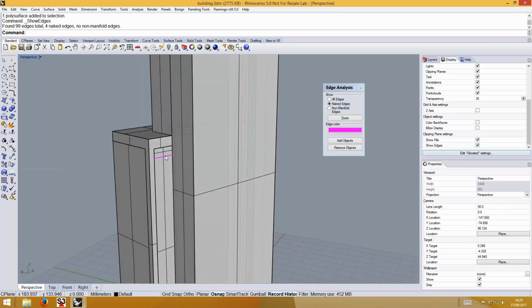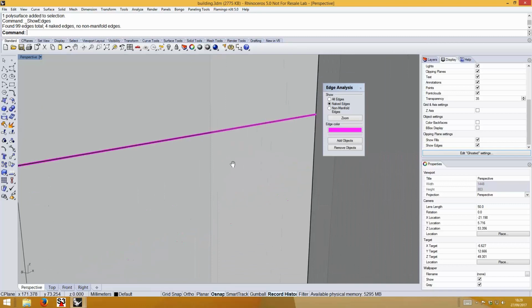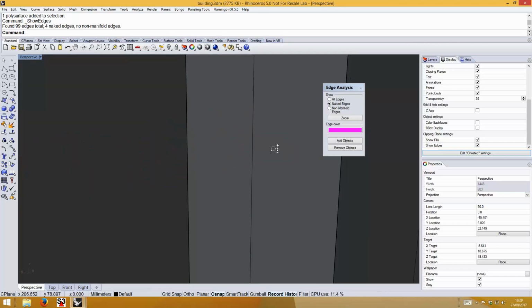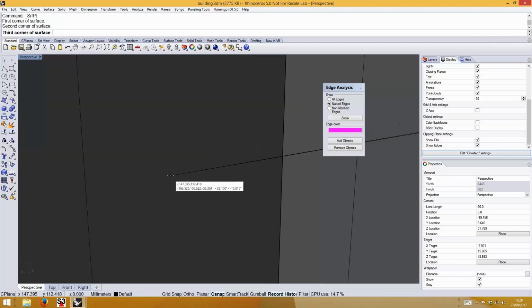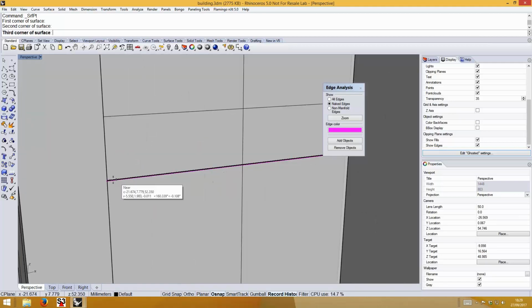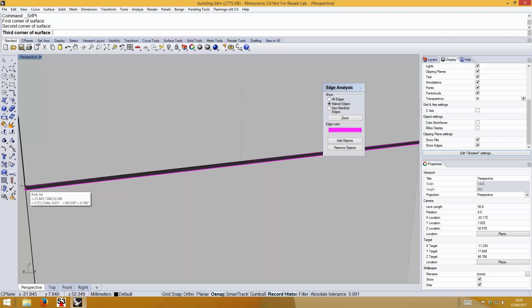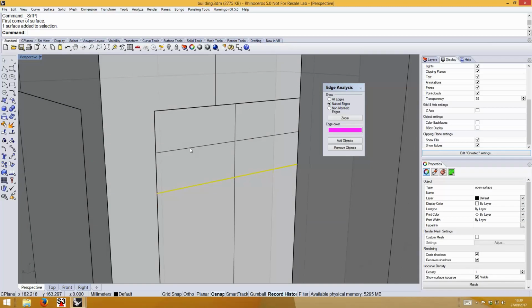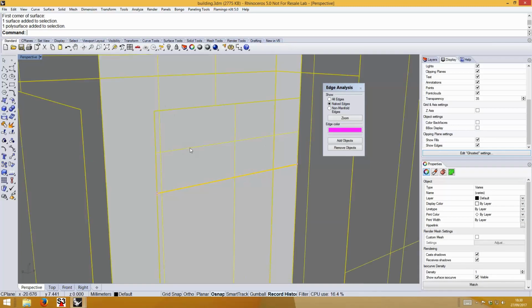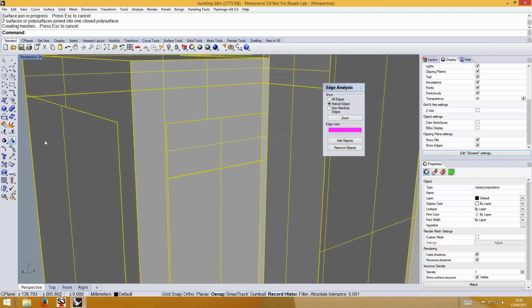here it is. In this case, since the gap is quite small but still visible, we could create a new surface that will just cover this gap, okay? So we might do that with just a very simple 4-point surface defining the 4 edges of the gap. Okay, there you go. If I now select this strip that I just made, hold Shift and click on the main building, then click on Join, okay?